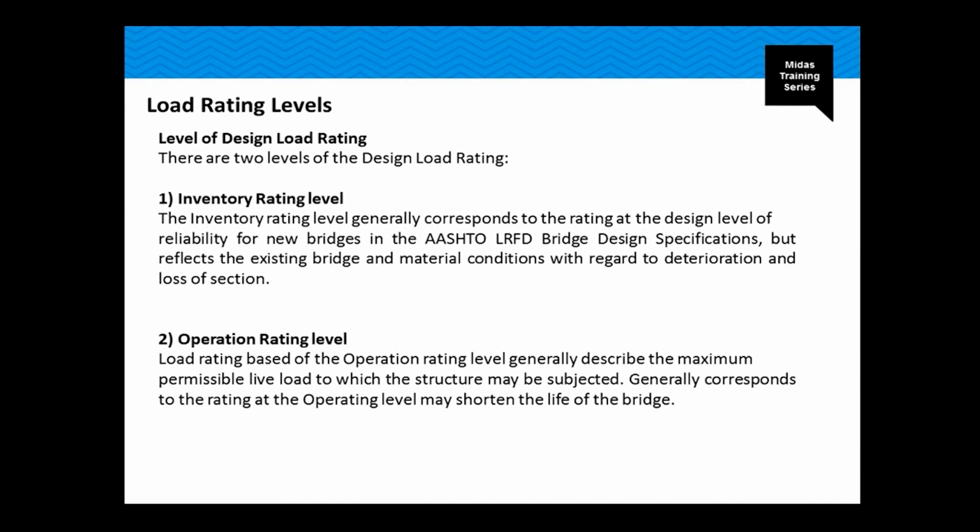For the level of design load ratings, there are two. There's the inventory rating level and the operating rating level. The inventory rating level generally corresponds to the rating at the design level of reliability for new bridges in the AASHTO LRFD, but it reflects the existing bridge and material conditions with regard to deterioration and loss of section. This is the most important part of the rating. It reflects the existing bridge and material conditions.